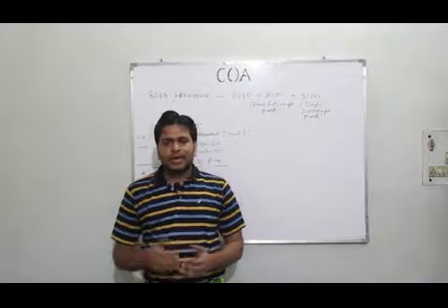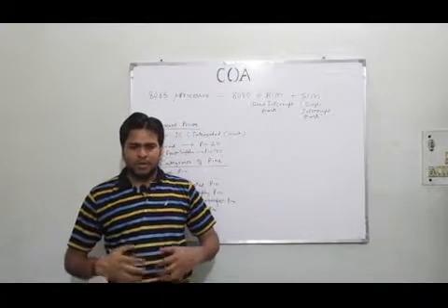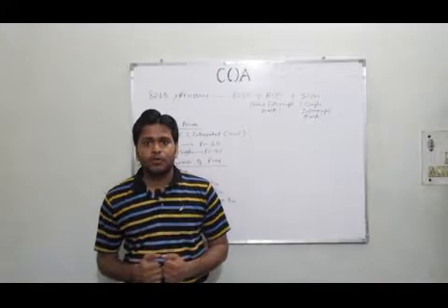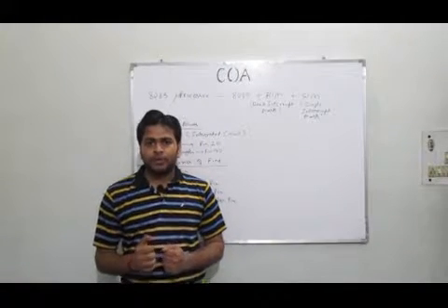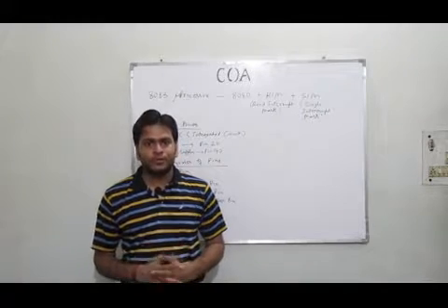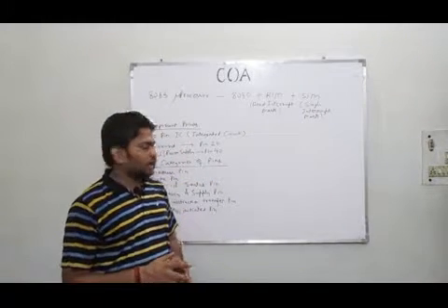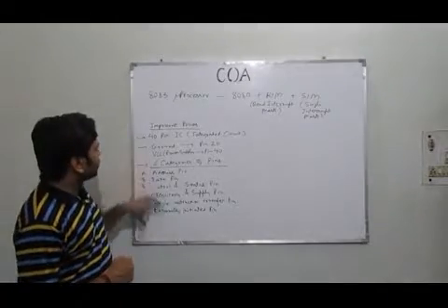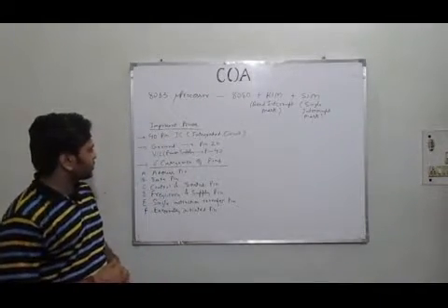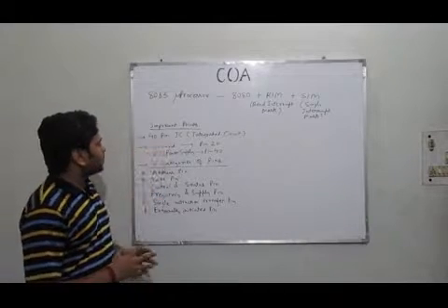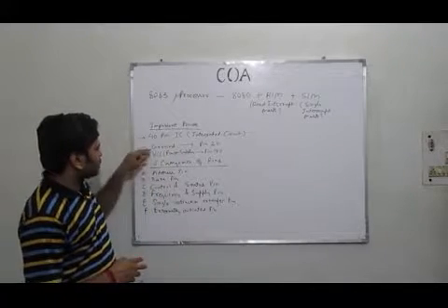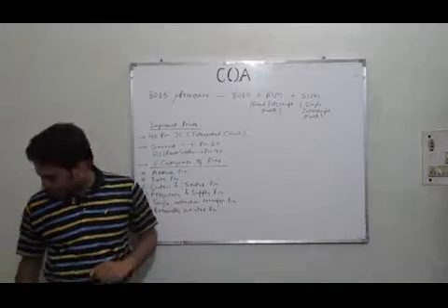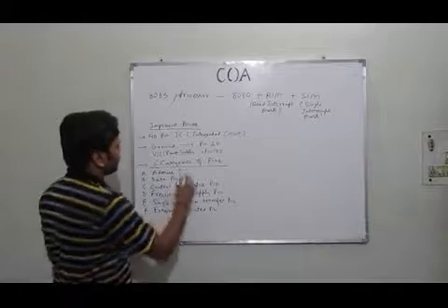In this lecture, I am going to discuss the architecture of the microprocessor in detail. It is a very important topic when you are appearing for an exam, viva or interview. In my last lecture, I discussed the configuration of the 8085 microprocessor, which includes a 40 pin IC where the ground is placed at pin number 20 and the power supply is provided at pin 40.